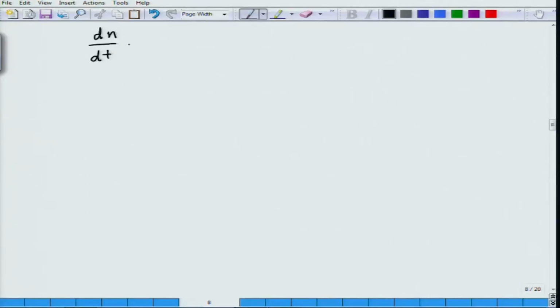I could always write it as how the concentration of holes is changing, because one electron will recombine with one hole. Now, this rate is going to be equal to the recombination, whichever mechanism, it does not matter, the constant will change. So, for any one mechanism, B times N times P minus the generation rate. I only put in excess carriers at T equal to 0. After that, the generation rate is G thermal.